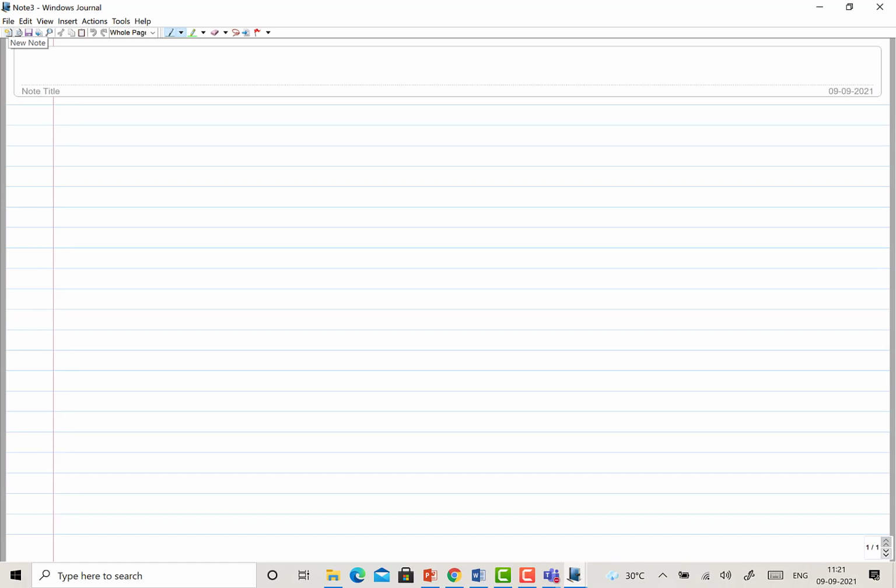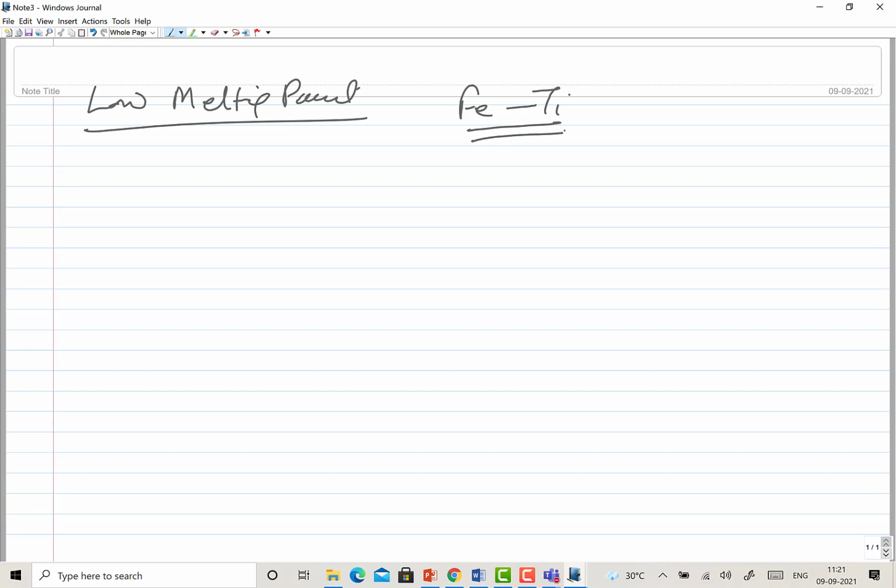Okay, the third situation or problem that is encountered is the formation of low melting point constituents. It's very common, especially when we are working with ferrous systems and titanium. Whenever ferrous and titanium are joined, they form low melting point constituents at the interface. Another example is aluminium and magnesium welding using friction welding.